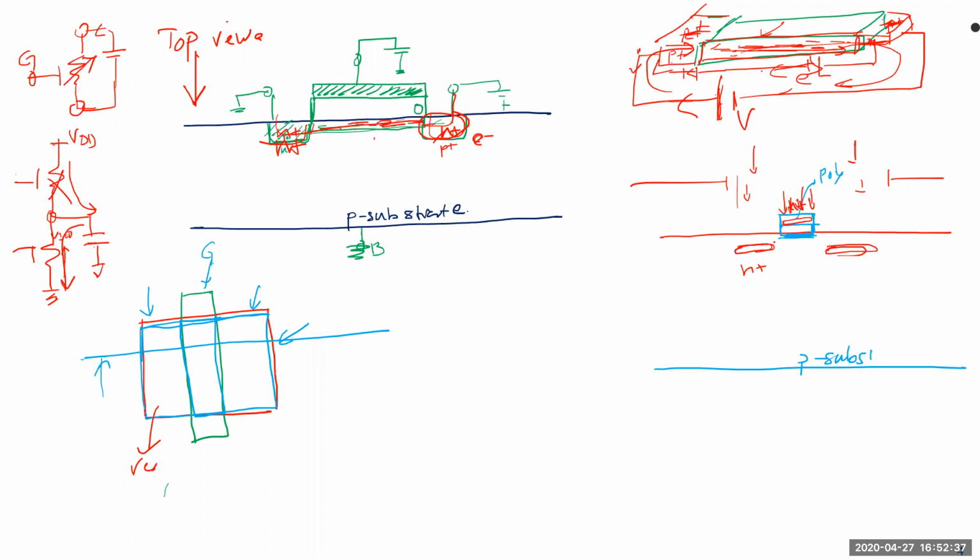And then what they do is they anneal it, and that's the heating process. When they anneal it, this whole thing kind of spreads. And this becomes N plus, and this becomes N plus, and obviously this gate area becomes N plus. And what they do after that is they do a small titanium or palladium to make it even more conductive, because you want this to be as conductive as possible, but you can't put a metal first, because once you put a metal and you heat it, it melts. The metal, like aluminum or copper, which is usually what's used for IC design, or tungsten, will melt.